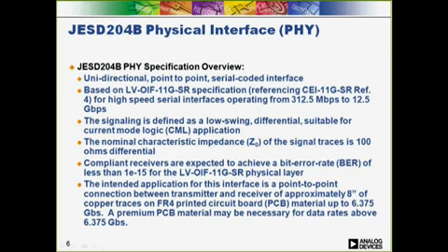The spec defines the intended channel to be up to 8 inches long on FR4 material up to 6 gigabits per second. It also calls for the use of PCB material with a low dielectric constant as the serial rates move beyond 6 gigabits per second.